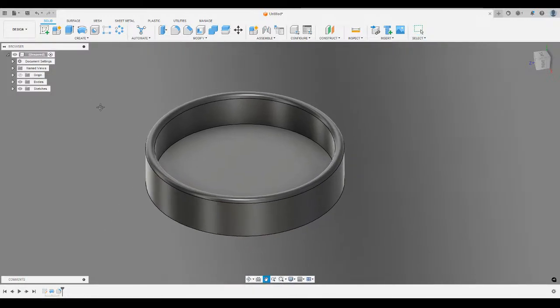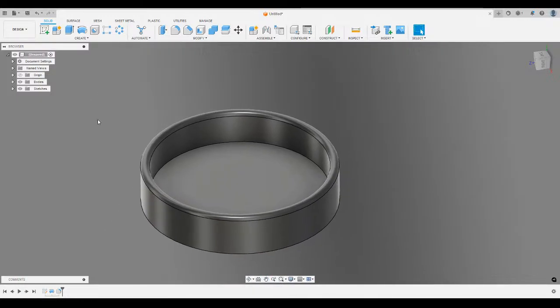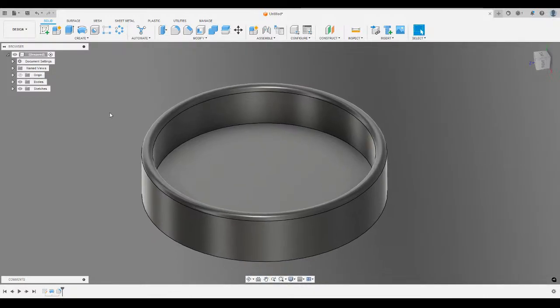Whereas if that 90-degree corner was rounded over with a fillet, and it had a radius to it, it would not have to fully stop moving. And that eliminates a lot of issues with 3D printing. That prevents you from having material buildup or blobs on your corners. That can increase your print time, your print speed, because your print head isn't having to come to a full stop and then reaccelerate back up to speed.